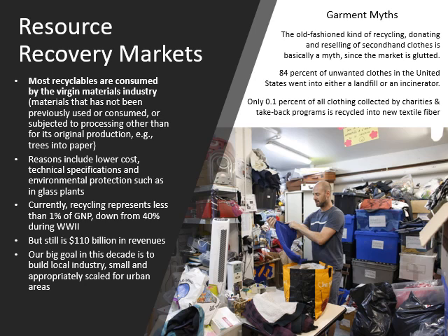Glass plants can, and this is a really interesting fact, when you melt glass for the first time, the ingredients for glass have to reach a threshold temperature. But if you throw recycled glass in, they call that cullet, it doesn't have to reach the same level of temperature. It can have a lower temperature, not a huge amount, but enough to make a significant difference in pollution and in energy usage. And so a lot of plants will just use 5%, 10% cullet just so they can meet air quality and energy requirements for their particular industry.